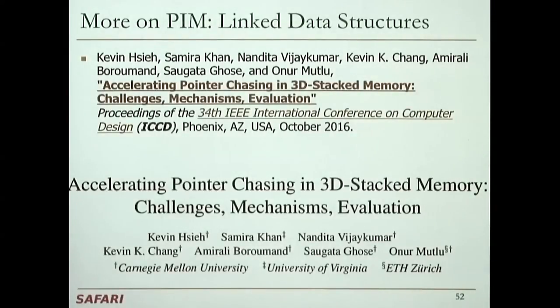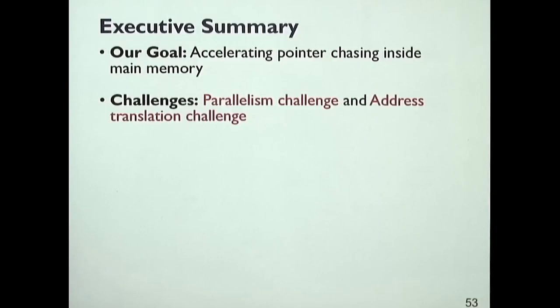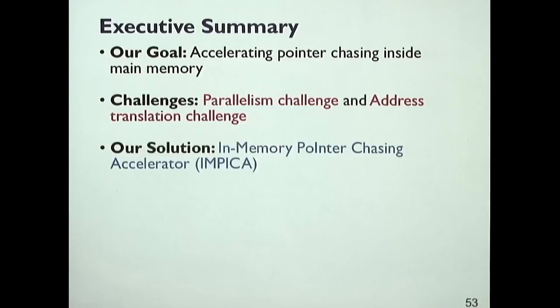But let me cover this, because it's actually interesting. It takes advantage of the latency benefits of 3D stacked memory so that you can execute linked data structures faster, and it proposes a specialized accelerator design inside the logic layer. So let me give you the very quick summary. Pointer chasing is an important workload. It exists in many, many places. And there are challenges in it if you want to accelerate it inside main memory. And we'll cover that relatively quickly.